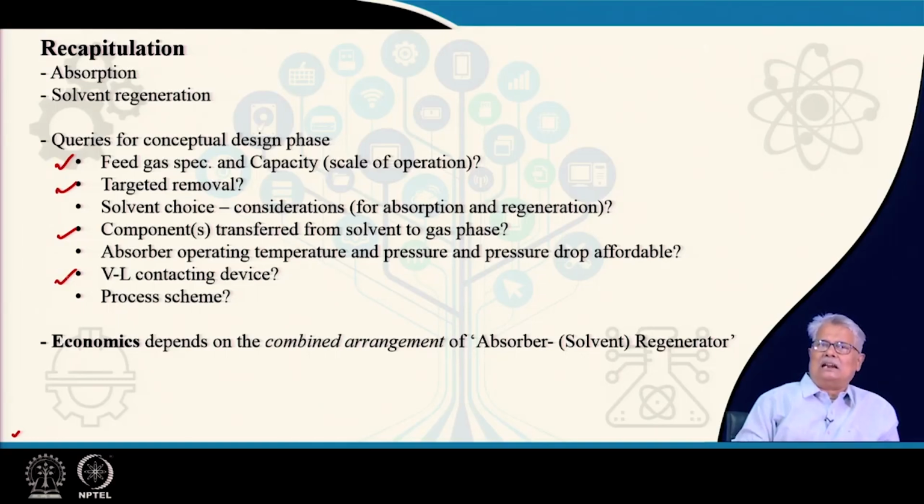It is not large. So, absorbers quite often will be using low efficiency trays like the sieve tray, because we can always provide quite a bit of extra number of trays to account for its inefficiency. Typical efficiency of a sieve tray will be of the order of maybe some 40% or so, it could be slightly less than that even.